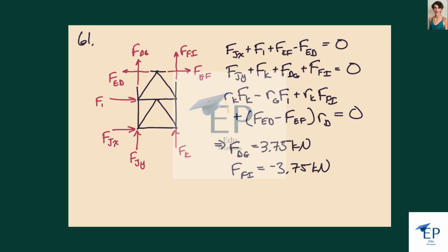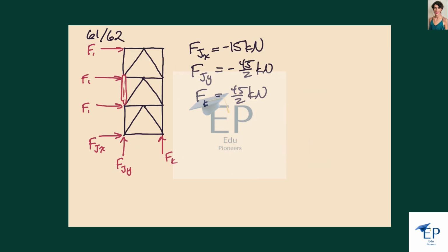And if we compare to the previous one, higher up on the structure, the forces in these members are lower than they are here, because these ones have to offset the moments created by all of these wind loads. Assume wind loads on this building. So as we go down, this one would have lower forces, and then middle, and then the greater. So we get greater forces in each member as we go down from the top of the building.